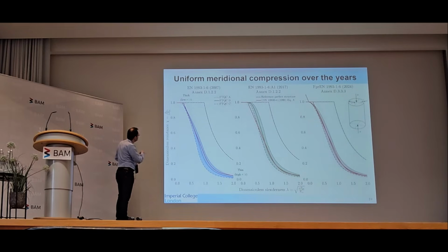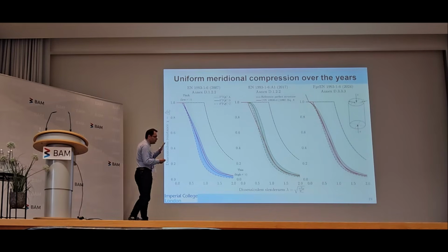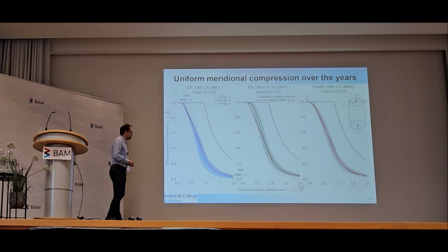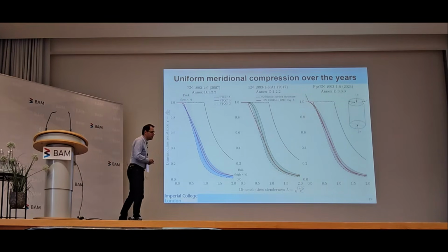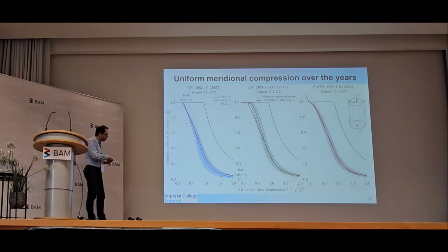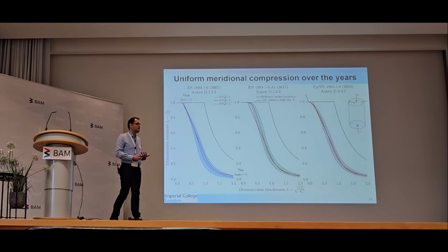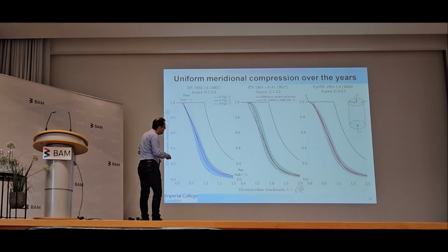Also shown for flavor is the old DIN rule, which is shown in red. It wasn't quite expressed in the capacity curve framework, but it was the precursor to it. The blue, the 2007 rule, you can see down here, I'm drawing your attention to down here. It was quite a conservative rule, particularly for the elastic region. So we had quite low predictions for the elastic buckling. In 2017, we changed that a bit. We brought that up so that it isn't so unnecessarily conservative in the elastic region.